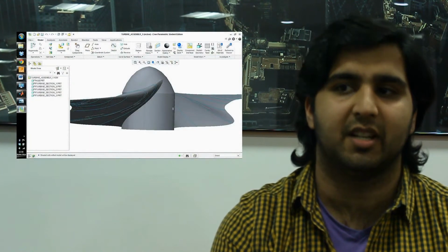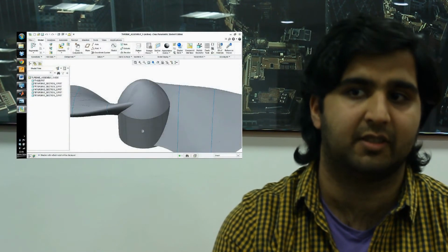As we approximated the blade as a beam, the structural calculations might not have been accurate. Therefore, as a safety measure, we decided to increase the chord length of the blade at the section which blended with the root to further reduce the stress. We also increased the pitch angle for this section to increase the lift and power output.